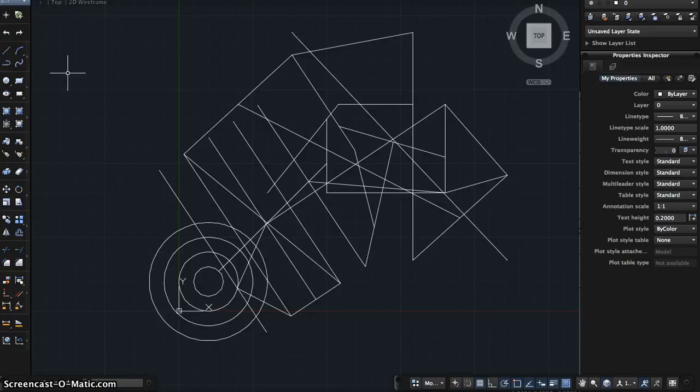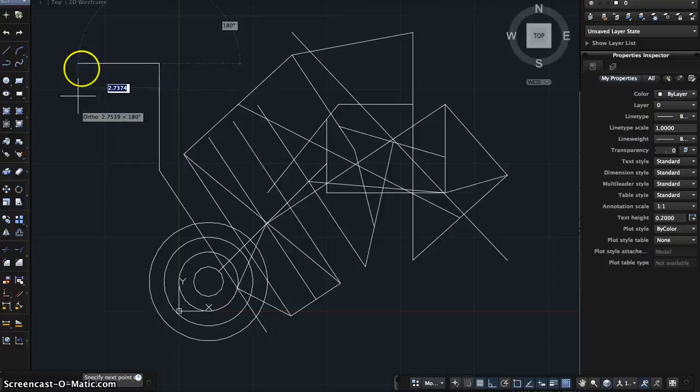So let's try it. Let's start writing line L. Let's start it, for example, here. As you can see, I can draw my line in any direction I want. But once I activate ortho, my line can be either vertical or horizontal only. I can't do any diagonal lines.